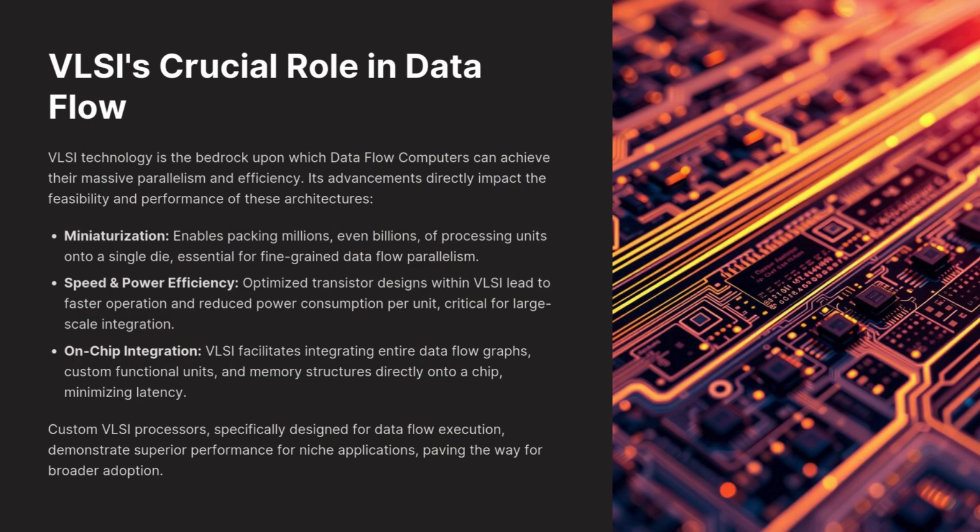And the limitations of VLSI. Heat: as chips get smaller, they produce more heat in a small space, making cooling difficult. Power leakage: at very small sizes, transistors can leak electricity even when they are off, wasting energy. Quantum effects: at the nanoscale, quantum behavior like electron tunneling can cause errors and make the chip less reliable.